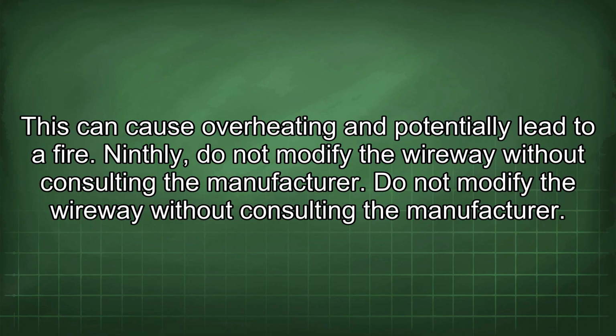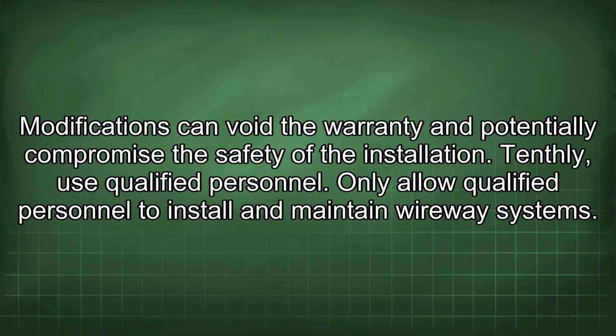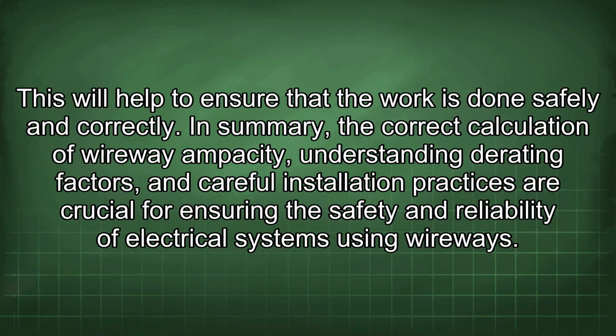Ninthly, do not modify the wireway without consulting the manufacturer. Modifications can void the warranty and potentially compromise the safety of the installation. Tenthly, use qualified personnel. Only allow qualified personnel to install and maintain wireway systems. This will help to ensure that the work is done safely and correctly.